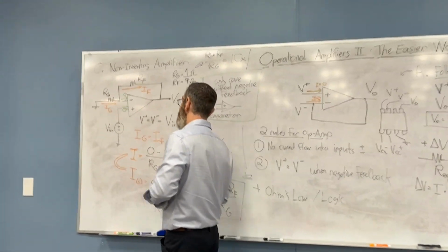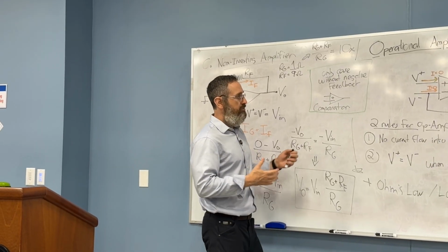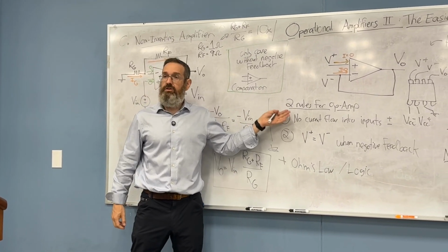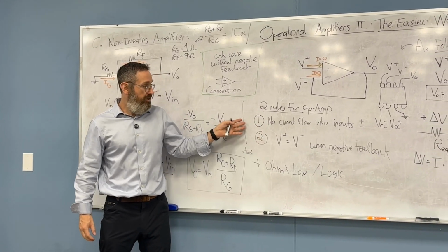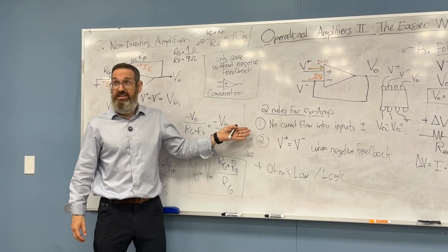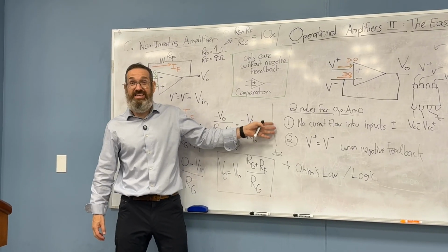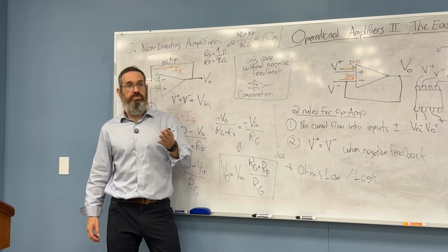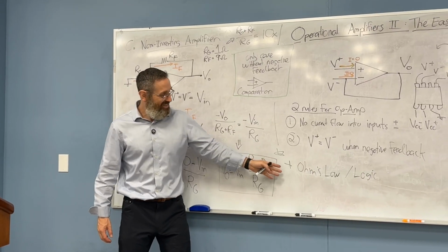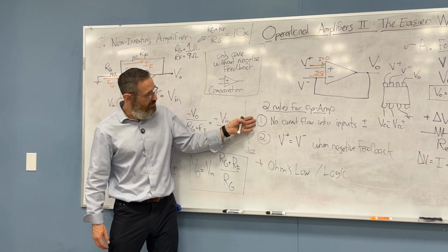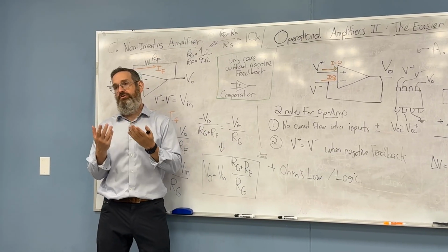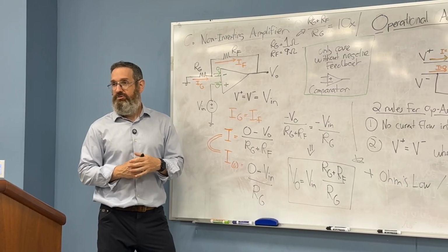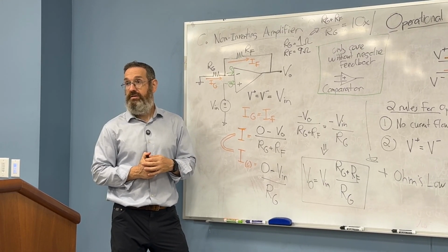And that's it. There is no op-amp circuit, and we will address slightly more complicated op-amp circuits, that does not bend the knee, okay, to these two rules. Once you apply these two rules, you don't have to worry about the op-amp anymore. Now there is some additional work. As you see, you don't just apply the two rules and the answer emerges. You have to apply the two rules, all right, and then do a little bit of Ohm's law, all right? Yes?